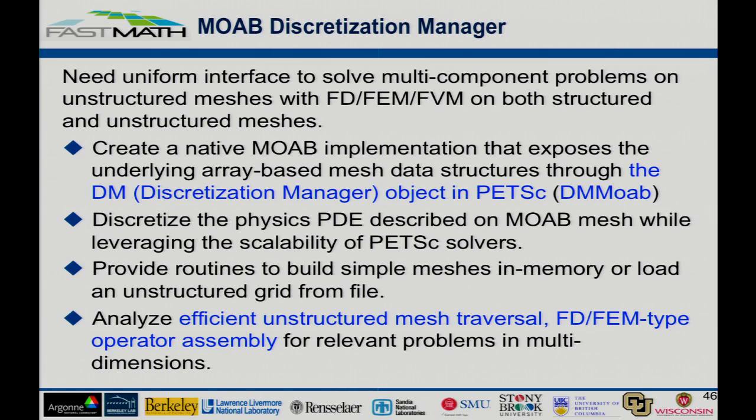And while doing efficient unstructured mesh traversal and defining your fields and creating your linear operators in memory, and then pass it on to the scalable PETSc solvers that are already available, both the linear, nonlinear, and the time-dependent solvers. So the DM pretty closely integrates well with all of those solvers.